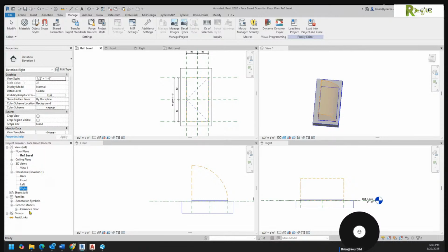You purge the job, you go in and purge the family, and you still won't be purging the objects that are in those nested families. So you've got to be really careful when making nested families. And on top of that, you have to be careful which ones you load them into, because that's where the mistake is.